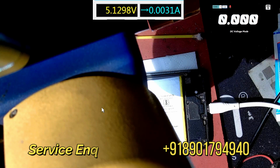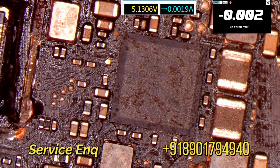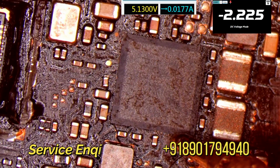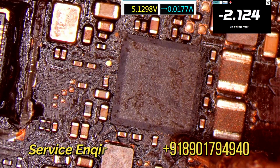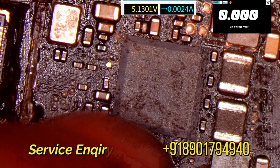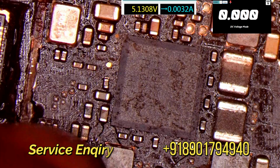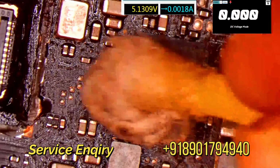Now under the microscope, right, let me check again on VPH on these capacitors. Now look at this, 2.1, 2.2, approximately 2 volts. So in a normal phone VPH gets 3.7 to 4 volts, at minimum it's 3 volts, but in this phone we get 2.1 or 2.2 volts. A similar voltage we get on VBAT, on the battery connector. Now let's check the IC number, which IC is used as the power IC, PMU.